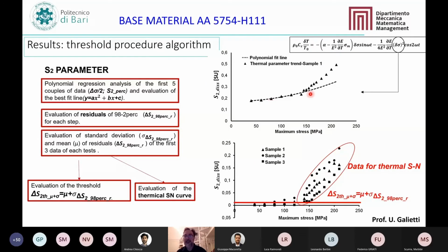So this is the second harmonic temperature change in terms of signal instead of temperature. And you can see, I didn't say that actually for aluminum and titanium, the second harmonic is not really straight. There is a small second order effect, but we can compensate for this because it just goes with a quadratic function. So you can see here the points are going as forecasted by theory. Here actually they are behaving in a different way. So this is the fatigue limit.